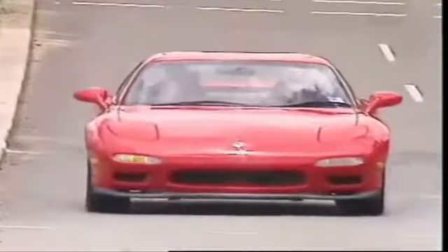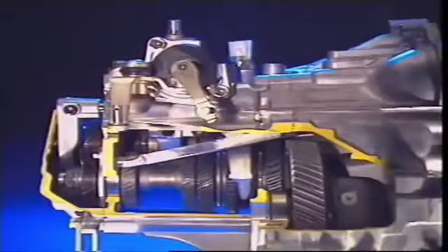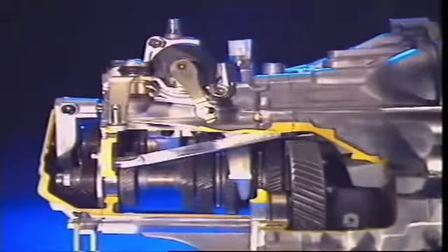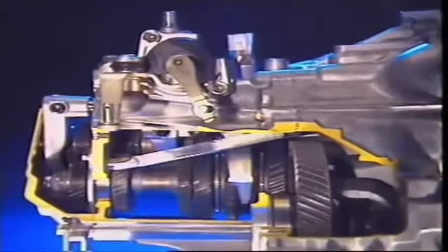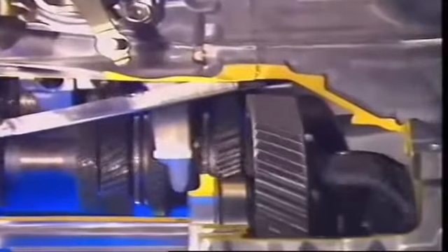A vehicle with a manual transmission uses a clutch to engage and disengage the engine from the drivetrain. Engine torque is transmitted through the clutch to the transmission or transaxle. The transmission contains sets of gears that increase or decrease the torque before it is transmitted to the rest of the drivetrain. The lower the gear ratio selected, the higher the torque transmitted.